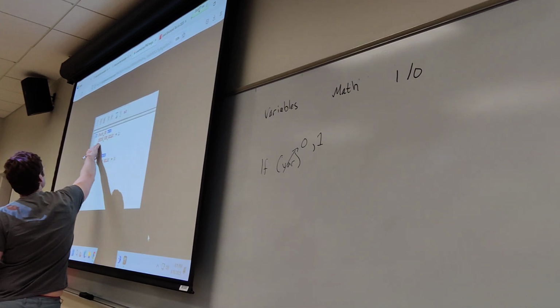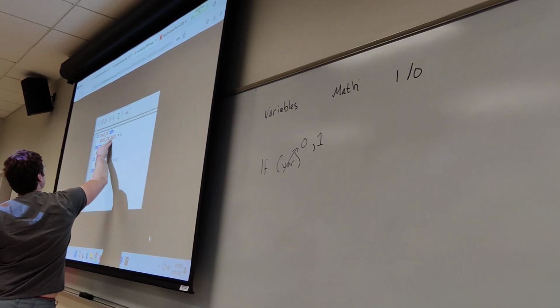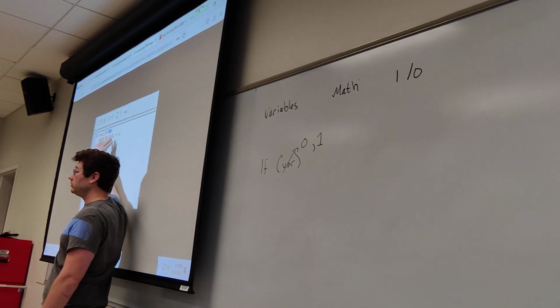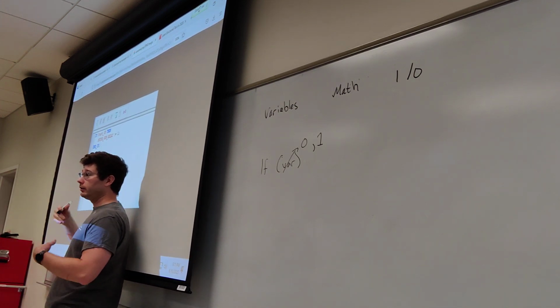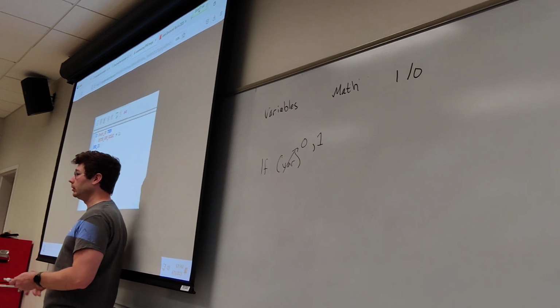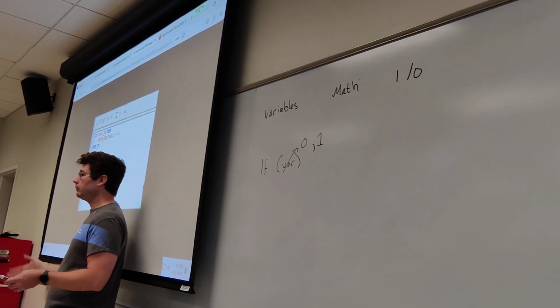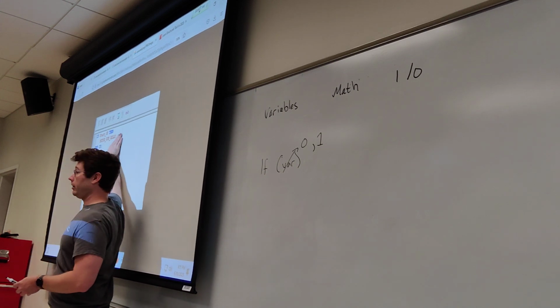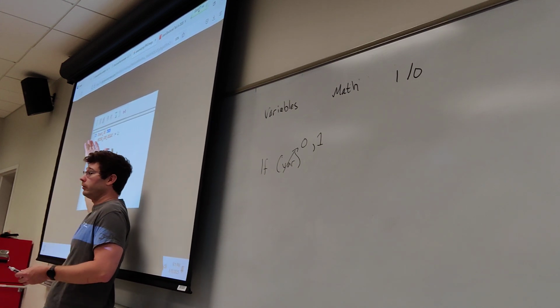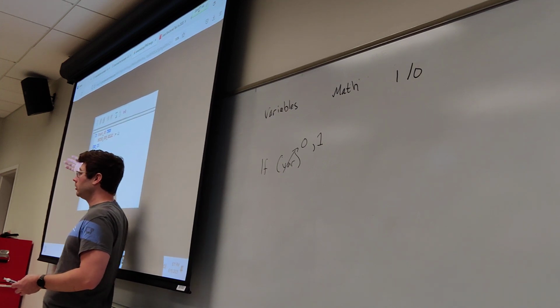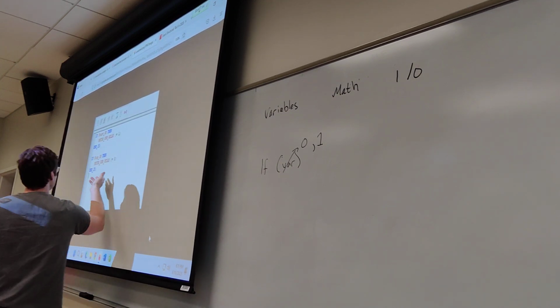This is how we assign something in structured text. Really the first and most important lesson of structured text, it's not simply equals like it is in a lot of programming languages, right? In Python, when you're setting a variable equal to something, it's equal that thing. Here it's colon equal that thing. It's kind of weird, but that's just what it is. If you don't do it this way, it won't compile. It'll complain at you, and it won't get where you want to be.